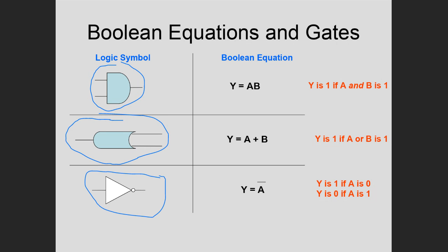So for this AND gate, I can draw the gate or I can write this. Now let me say something about the Boolean expression for AND. Think of that like the multiplication operator, the little dot operator. I didn't show that on this PowerPoint because I probably didn't know how to make a dot at the time. But there's really a multiplication sign between the A and the B. So this should really say A dot B, and the dot is the operator for AND logic.